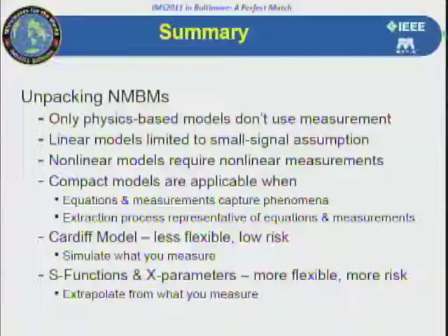If you think you're just going to do some linear measurements and get a nonlinear model by varying it over bias, well, I guess to quote my daughter, that's so 1980s that you really should maybe think about changing your model type. Compact models are measurement-based. The risk in using compact models or the magic in compact models is the extraction routine and whether the right measurements were done to map those model parameters from that measurement data that you have.